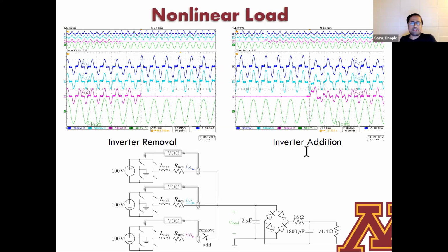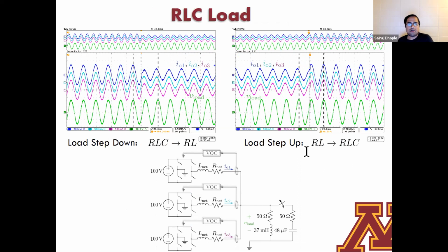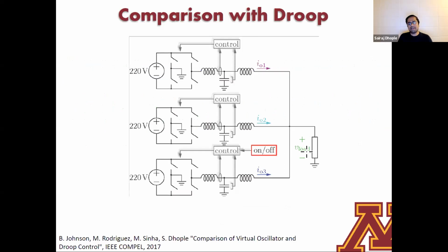All right. What happens if you have RLC loads? Again, this is now just running through the motions here, but you can provide a wide range of power factors and still get all of these desired behaviors of synchronization, of fast dynamic performance, and so on. So here's just a sample set of waveforms where I'm going between capacitive loads to inductive loads and back, and still able to see all the desired properties and performance attributes as I did see from before.